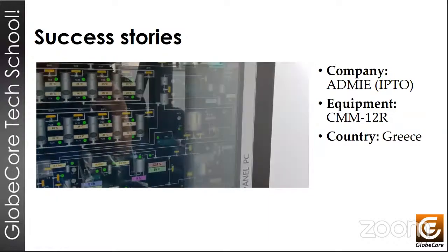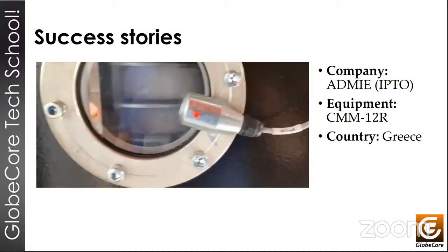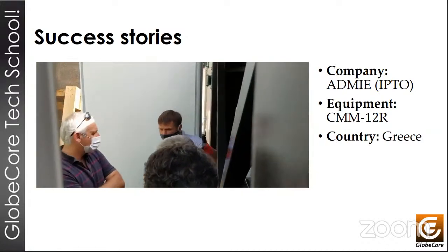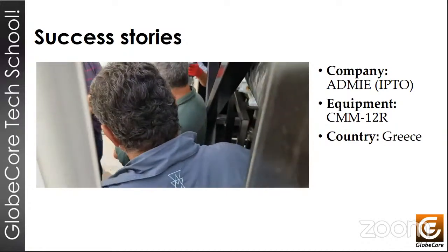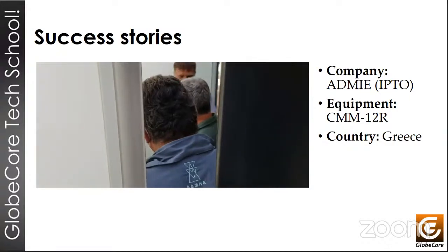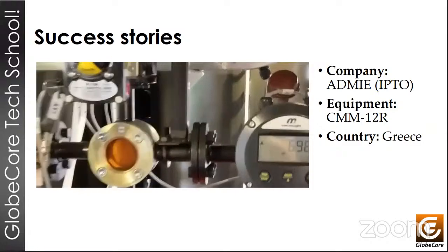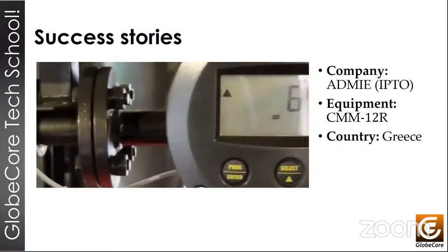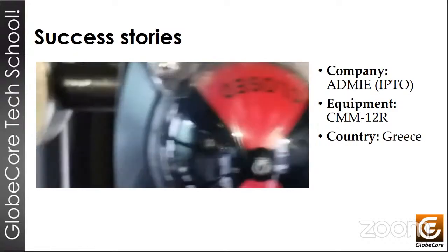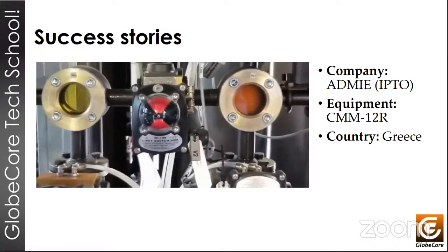And this is a cycle that can be repeated over 300 times before we actually have to replace the Fuller's earth. And okay, just one thing, when we replace Fuller's earth, we run one last reactivation, burn out all of the contaminants from that Fuller's earth, and then it turns into a very inert powder that is not toxic, not hazardous, not anything. So you can treat it as sand pretty much. Okay, next slide, please now.